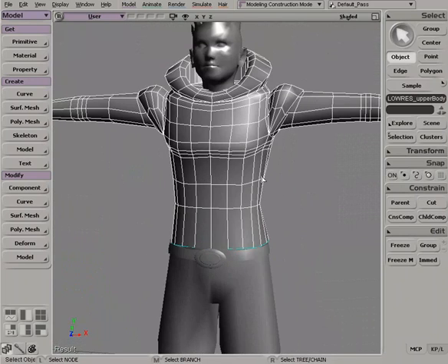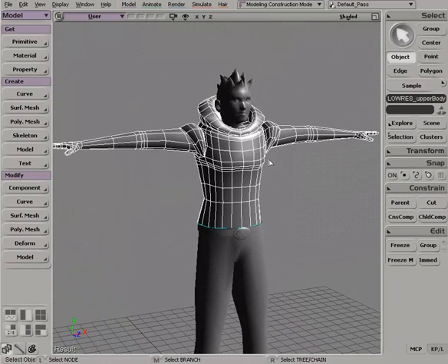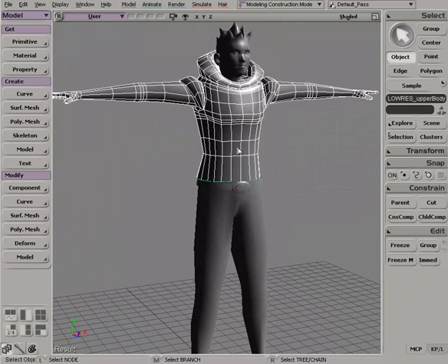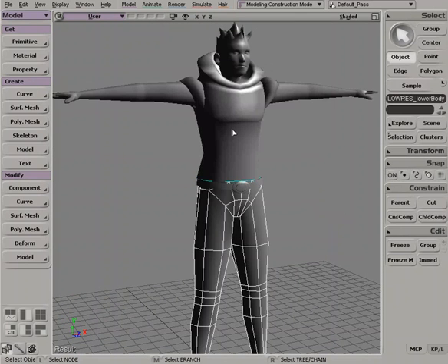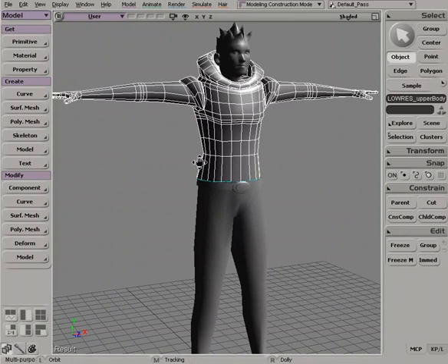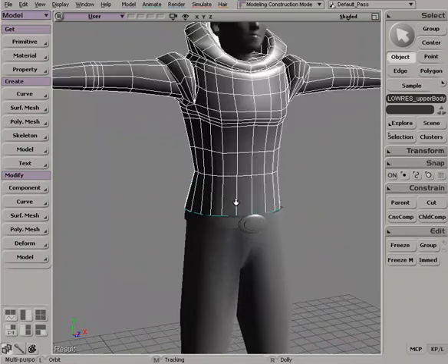Right, so now that these UVs have been created and this object has been UV laid out, remember we only need to UV lay out the low-res object. So once we do this, what we need to do now is begin the process of taking all these different meshes and actually merging these down into one solid continuous mesh. So in XSI, that's actually very simple.